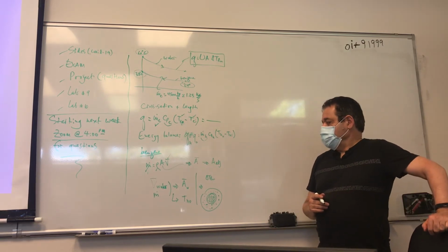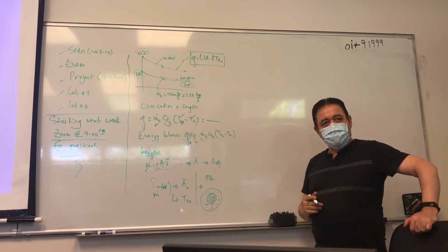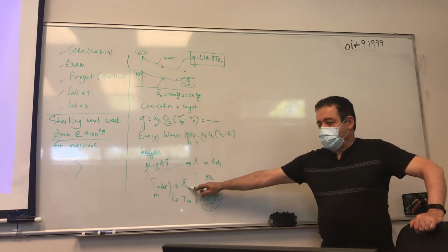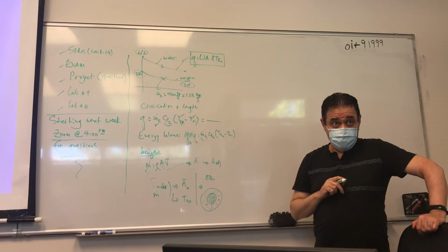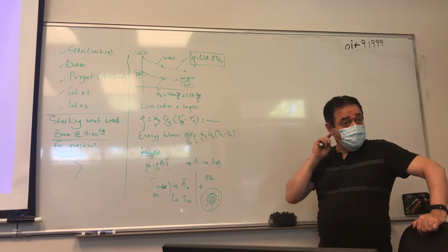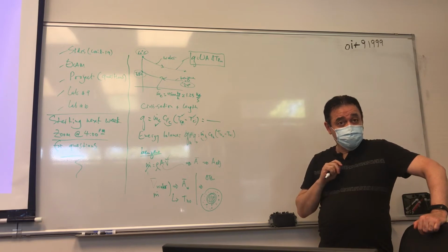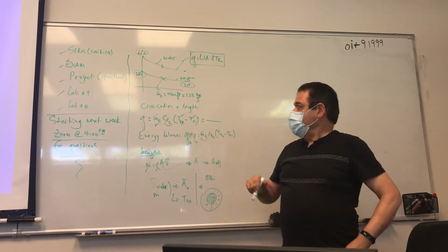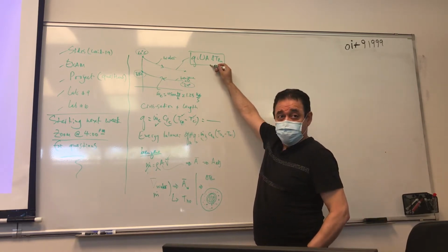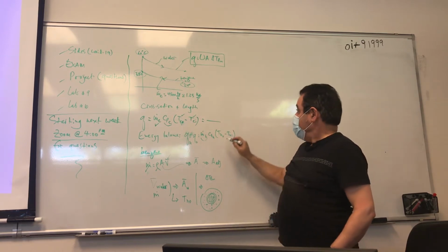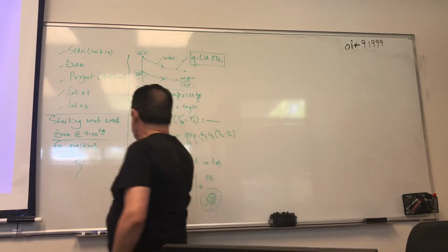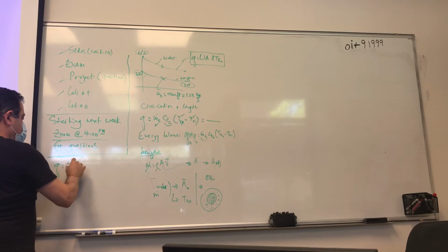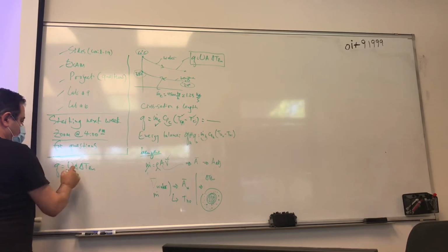Find your area or your total. From your area you can get your length. But these areas are what? They are cross-sectional areas. You cannot find a length from a cross-sectional area, it doesn't matter. So how are you going to find the length of the pipe? Well, that's where this equation comes into the game. Remember, in that equation, Q is equal to UA delta T Ln, right?